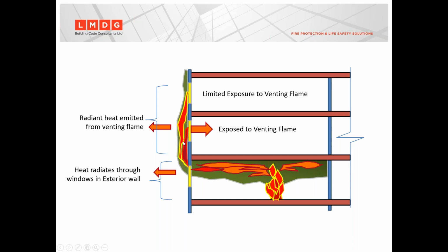Of course, if that wall is clad with a combustible cladding material, that fire is going to have a much easier job of spreading. And the test, therefore, is determining how much heat does that combustible cladding radiate away from it? Could it catch an adjacent building on fire because so much heat is radiating? The other thing is, how high do the flames climb? Are we risking the fire busting back into the building a couple of floors up and skipping floors and accelerating its way all the way up the building?